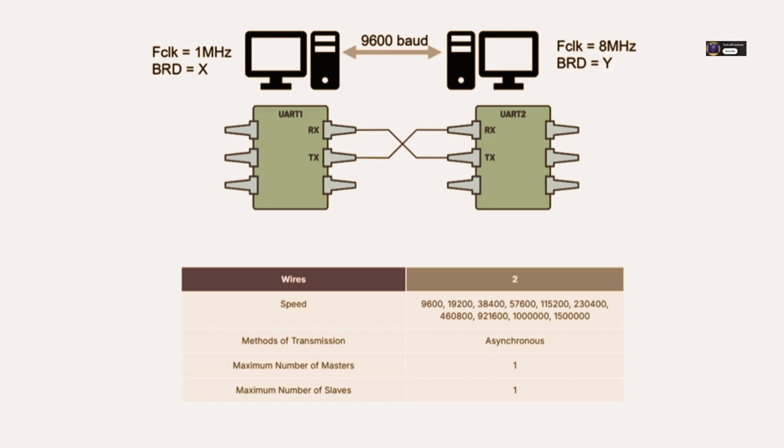That dedicated UART task would spend most of its time blocked waiting for data to appear in the queue, using something like xQueueReceive. When the ISR puts data in the queue, the RTOS automatically unblocks the UART task. The task then reads the data from the queue, processes it, parses packets, acts on commands, etc., and then goes back to waiting on the queue. You might also use RTOS semaphores to signal data readiness between the ISR and the task. This approach keeps your ISRs very short and fast, critical in an RTOS, prevents UART handling from blocking other important tasks, and neatly encapsulates the communication logic within its own task, making the whole system more organized and responsive.